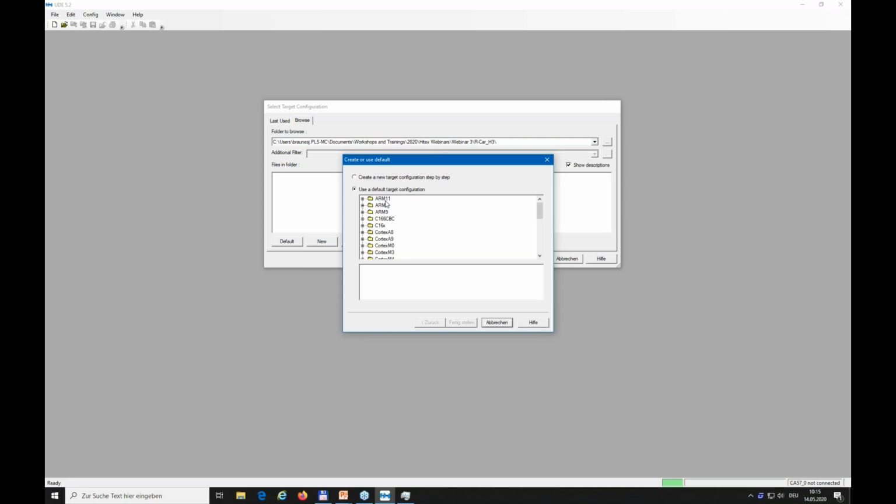You see a list of the target architectures, beginning with all the ARMs, then some Cortex, power architecture, TriCore, Oryx, and so on. And we have here, for example, the R-Car H3 starter kit with 2 possibilities to connect using SWD: booting from the A57, which is what we want to use, or booting from the R7.